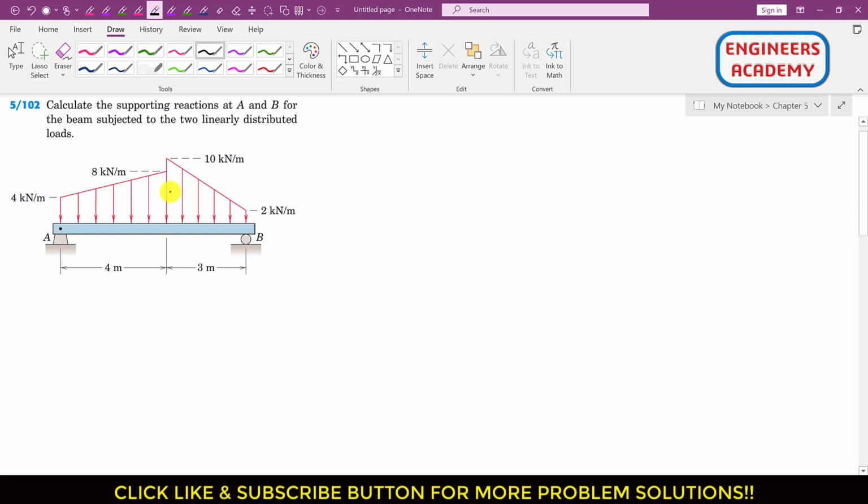There are two methods to solve this particular problem. One method is that you can replace this one distributed load by a single resultant, and replace this other distributed load by a single resultant. The second method is that we can replace this whole distributed load by only one single resultant. I will try to solve this problem using both methods. First I will replace this whole distributed load by a single resultant.